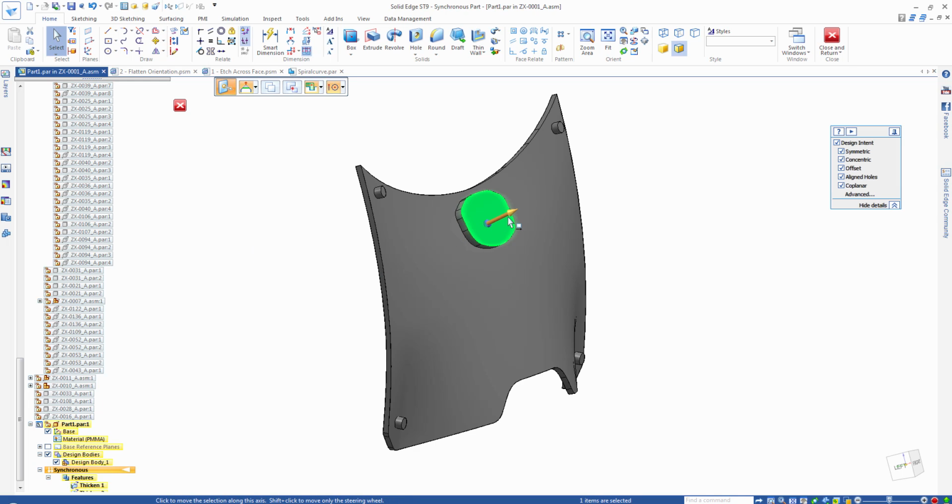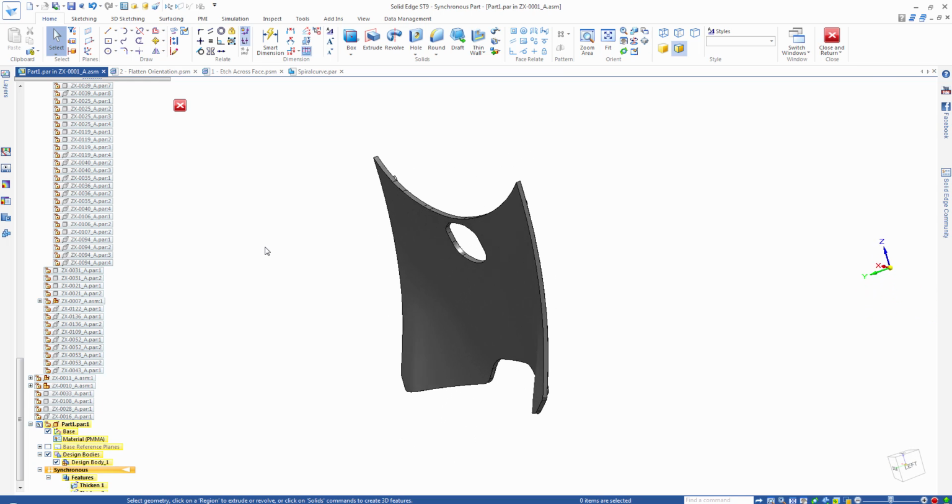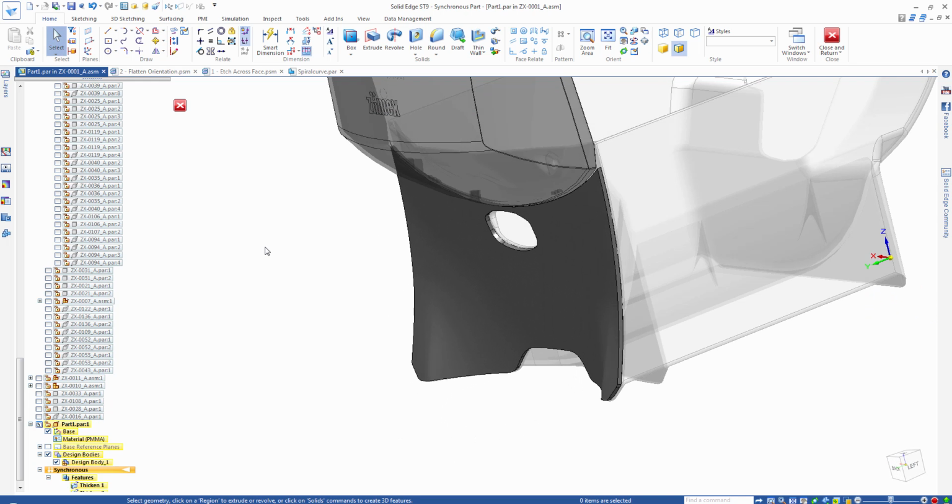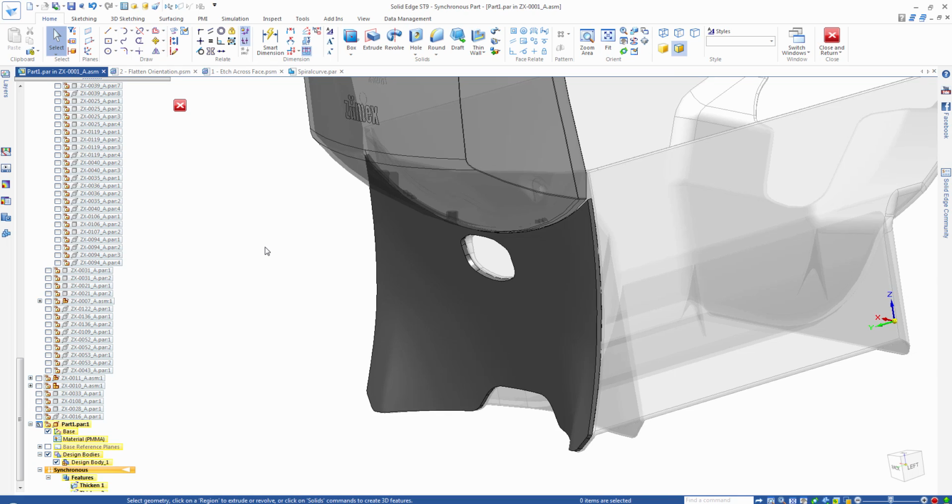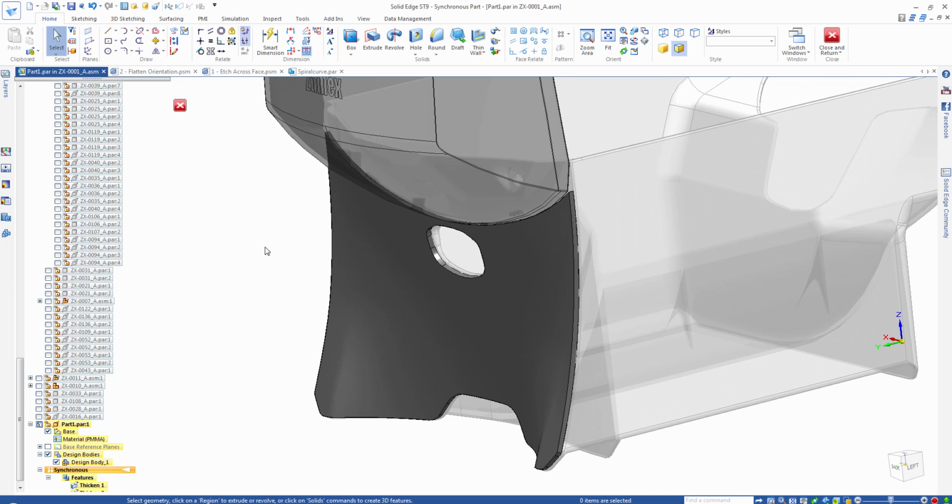And this I actually need to cut out because it's part of where the spout comes through. So I'm just going to extrude that guy back 10 millimeters and create the cutout. So just like that, without making any surfaces or anything like that, I can grab the existing geometry, thicken it, and get that component to fit perfectly the way that we need it to go.